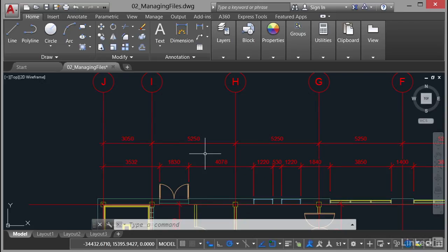Now would that be 1830 inches, 1830 kilometers, 1830 miles? It's not, is it? It's got to be a sensible dimension in context, and that's why you set your units. So you can see here that that's 1830. That would be 1830 millimeters, which is a little bit under 2 meters. So that's roughly 2 meters at that opening there. If you rounded it up loosely, 2 meters, but it's 1830 millimeters or 1.83 meters.